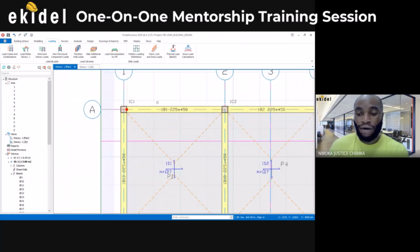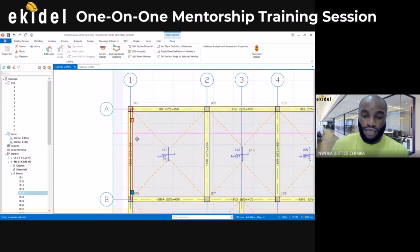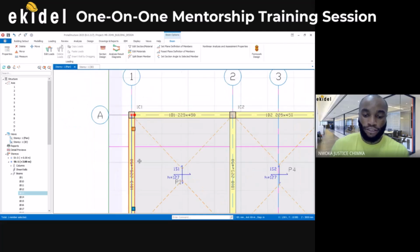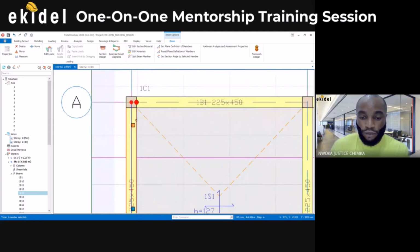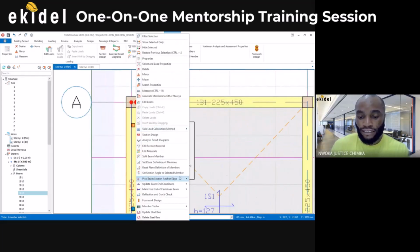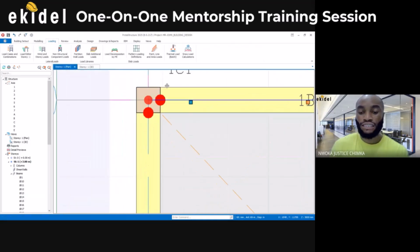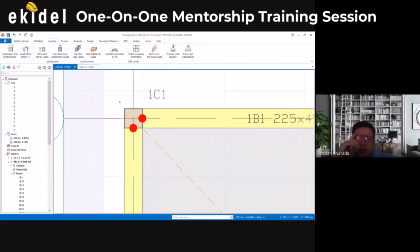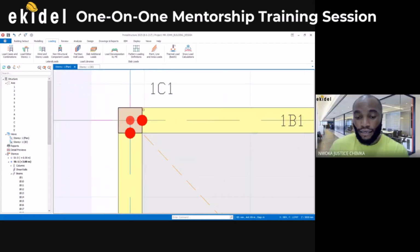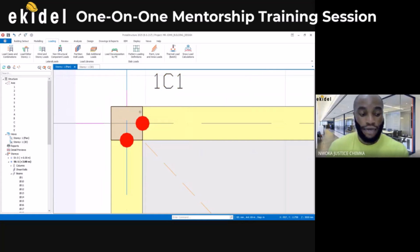So with that now, I'll do the same for the rest. Here also, this beam has an end at the J, but the I is not an end because there is still a beam which shows a continuous end. So I'll click on this beam, right click and say update end condition at J, then update and apply. You can see it here. So with this, I have freed the moment around this place. So you lessen the negative moment at that point, so it doesn't require that much steel at the top. Exactly, at this place.